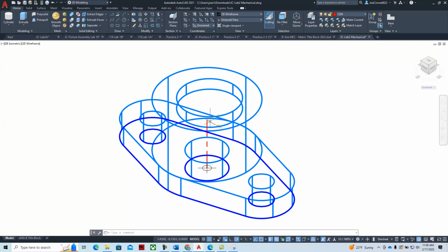Then if I wanted to, I can create the orientation of that cylinder, but I have to change the XY axis of rotation, because you always draw in the XY axis, meaning this will draw a circle right here. But if I want that circle to be at a different angle, I can say UCS and then rotate it. I just do it by eye. I'll say rotate it about the x-axis, 90 degrees, and see if that's the one I want. It's almost the one I want. It's going the other way.